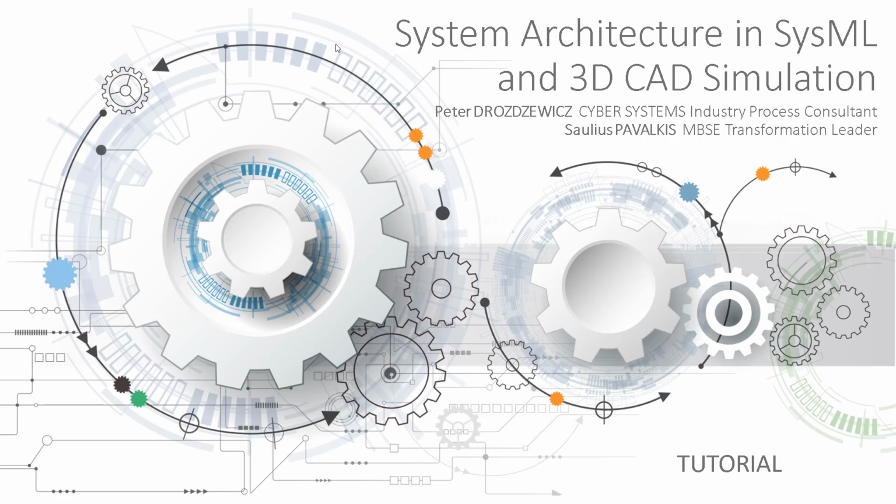What's the motivation? This is one of the most common MBSE ecosystem requests in SysML and 3D CAD integration. This is alignment between two major disciplines, system engineering and mechanical design. In this tutorial, we will present an out-of-the-box method to leverage simulation orchestration tools like Process Composer from the 3DExperience platform to integrate SysML and 3D CAD models to enable simulation and analysis. This tutorial enables application of this method and tools in multiple domains and use cases.